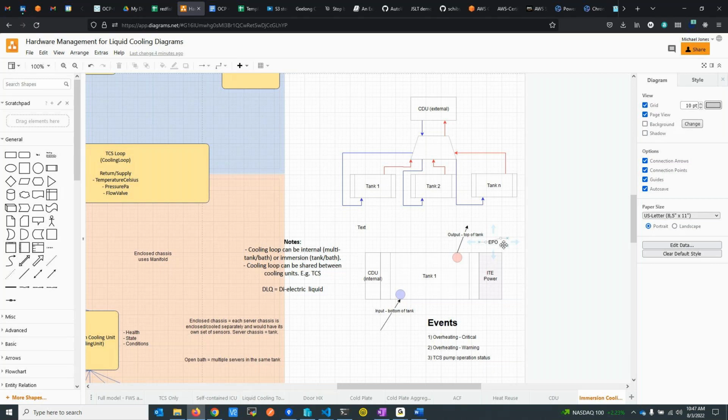And then if that doesn't help, there's a dramatic fallback for clock speed and voltage. And if that still doesn't work, then you power it off to protect the chip. So regardless of what the cooling does, it's got a self-protection mechanism in it. Yeah, so that's pretty much standard. It's the same with air cooled. It just starts to throttle back until it has a thermal shutdown.